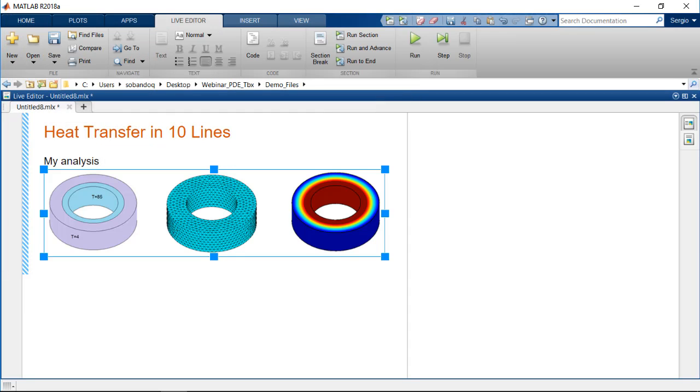The PDE workflow typically involves the following 3 steps. First, create or load a geometry and generate a mesh. Second, determine the type of model and boundary and initial conditions of the system. Third, find the solution of the FEA and visualize and post-process the results. Let's start with the first step. Consider heat transfer or conduction in a pipe.